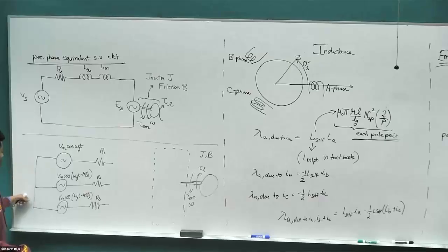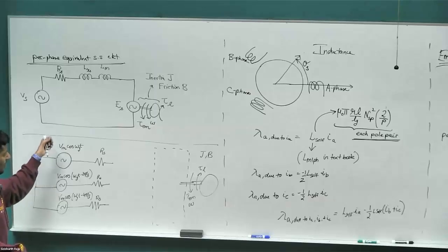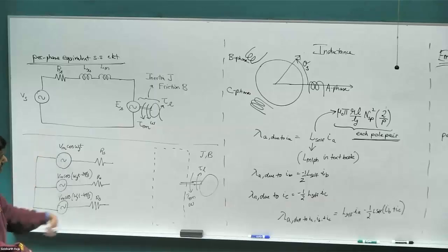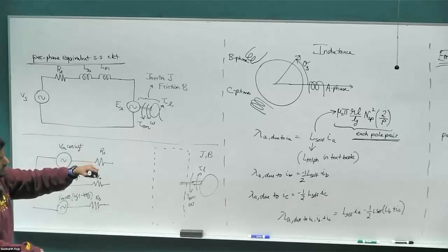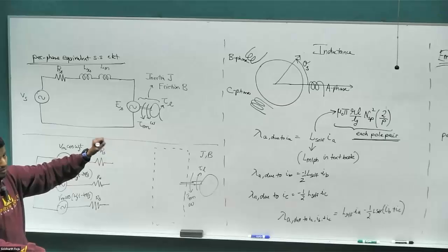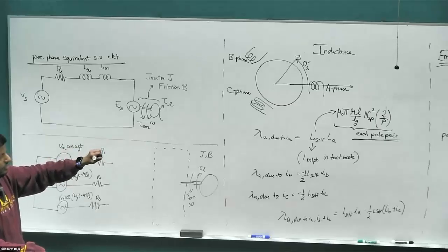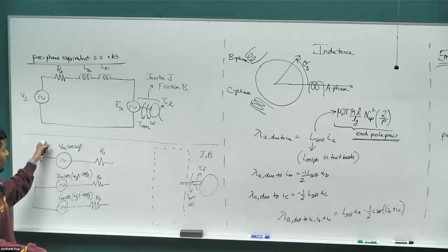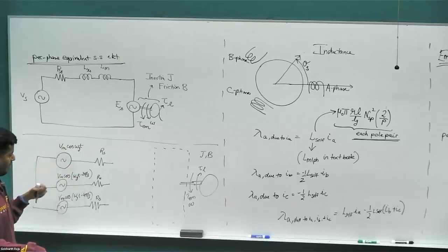Right? So we have 3 individual voltage sources applied on each of those phases. And the only requirement is that these voltages be balanced so that the motor currents are balanced. The equations that we have derived so far, none of them require the voltages to be assumed balanced. We derived for generic currents, generic voltages, but going forward, we are going to assume the voltages are phase shifted by 2 pi by 3, and the magnitudes are all constant, for the steady state equivalent circuit.